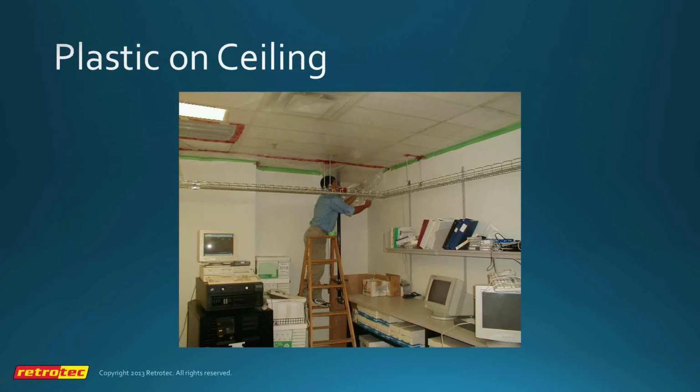So to answer your question, the first way, and the obvious way of doing it, is simply to seal off the suspended ceiling so that we are isolating the lower leaks from the upper leaks. So typically, enclosures tend to leak more above the suspended ceiling. They just don't put the effort into sealing up there as well.